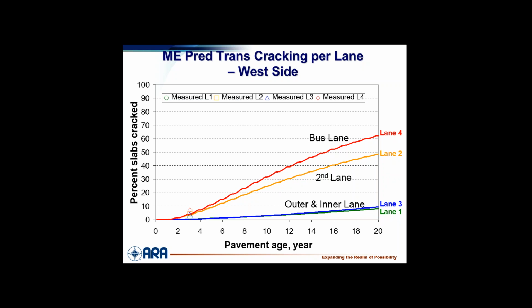Geez, that's a good question. 5 meters, probably maybe 4.5 meters. It was pretty good, and they actually doweled the joints. They doweled the transverse joints, but the longitudinal hardly had any tie bars in them, and that's another thing. There's no load transfer, so we modeled that more or less as 20% or something LTE.